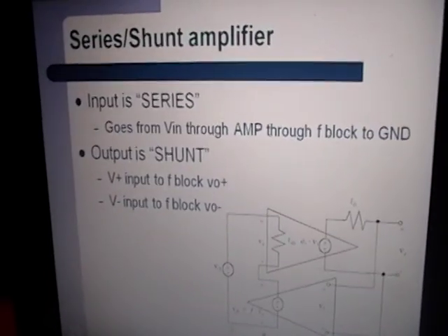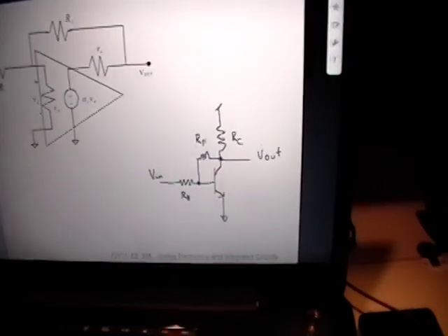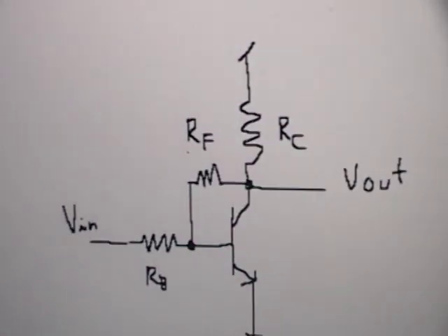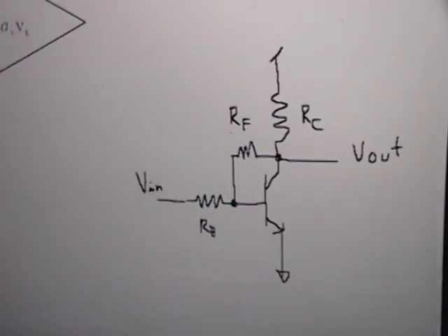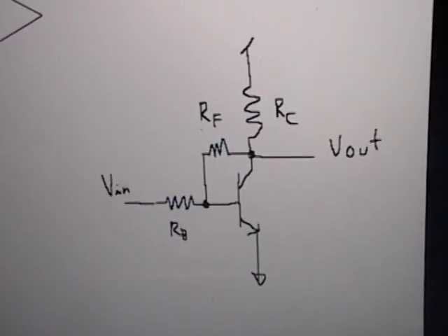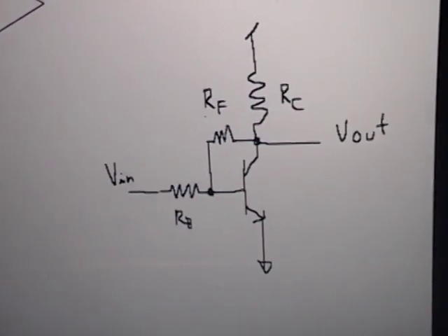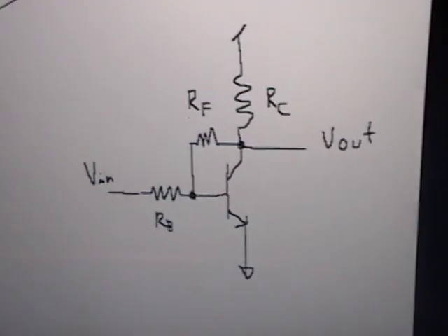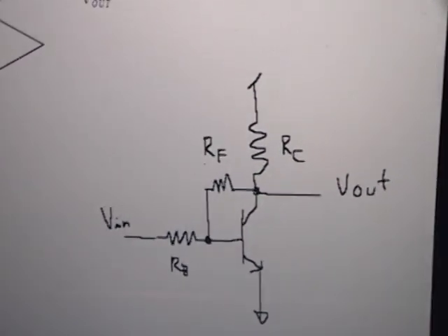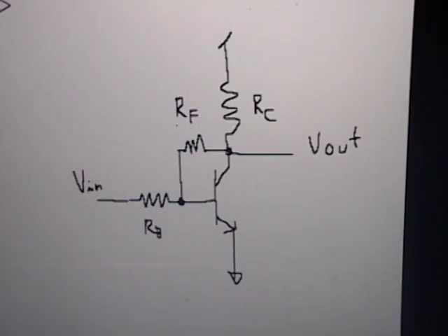All right, and let's do another one. If you look at this one, first you have to knock out your vanilla amplifiers. So right there I see a common emitter, and RC is a necessary part of the common emitter. So I see that as my AV. That's my feed forward amplifier.